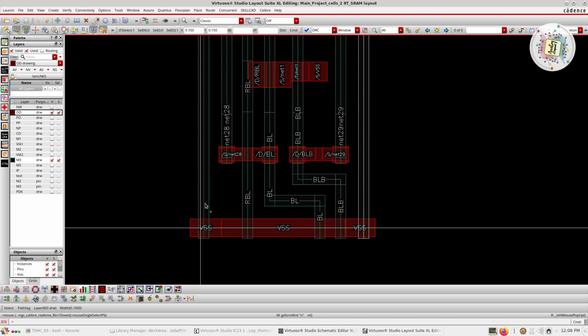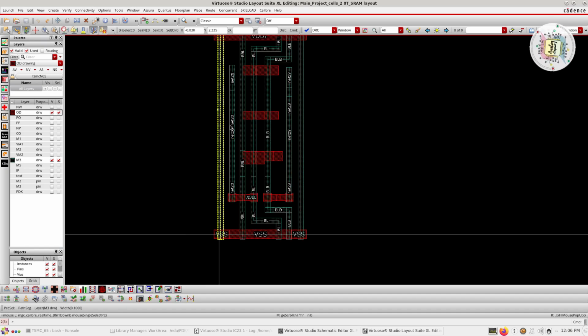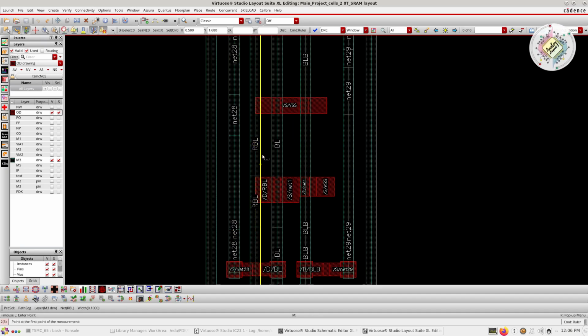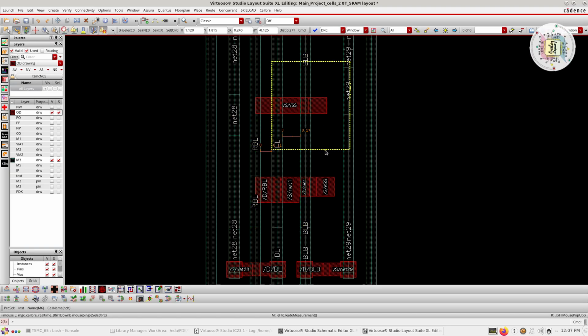So I have reserved the metal routing inside the subblock level itself. This is my T-2 level, but these routings are going to be utilized in the T level, that is my top level, or maybe the T-1 level. But inside the T-2 level itself I need to reserve the area here. And moreover, in this block I always need to maintain some minimum DRC between metal to metal, that is 0.11. Somewhere I cannot maintain minimum DRC, so that doesn't matter. That's what we discussed in the previous video. We cannot always maintain the minimum DRC, or the theoretical routing structure here.